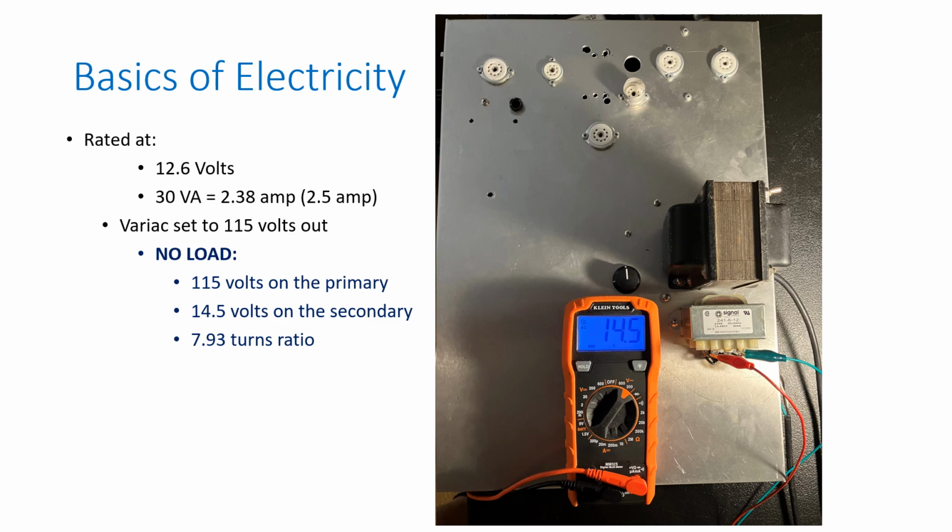Well, this is actually how transformers are designed. Because when I talked before about voltages on the secondary, I'm talking about a no-load output. Once you put a load on the transformer, because of the physics going on in the transformer, the output voltage can't stay the same. It's going to drop somewhat. If you put a very light load on it, it won't drop. But if you put any substantial load on it, it's going to drop.